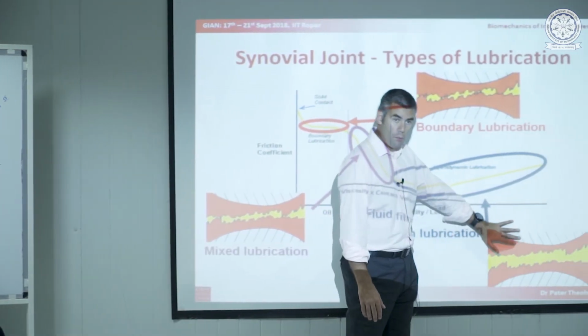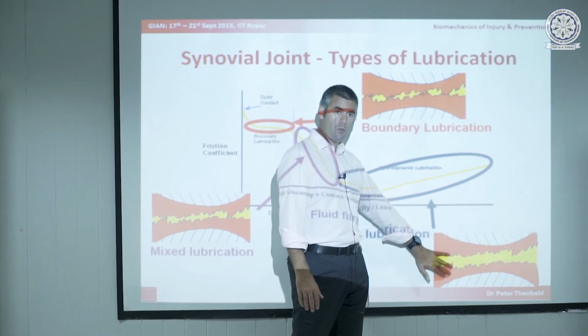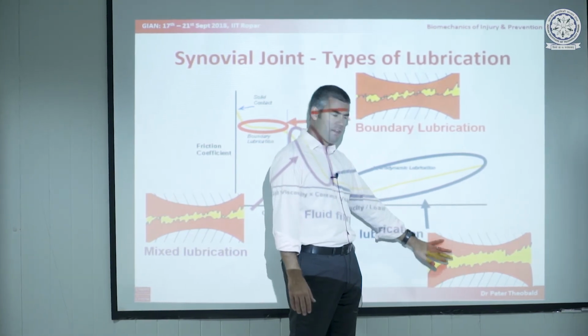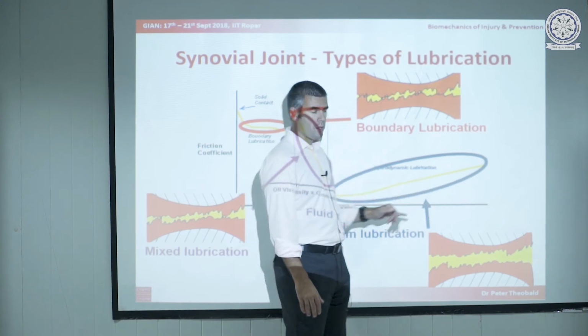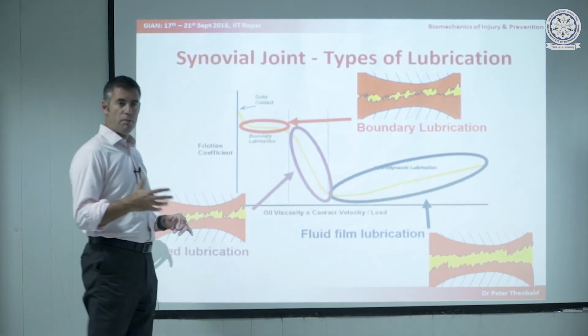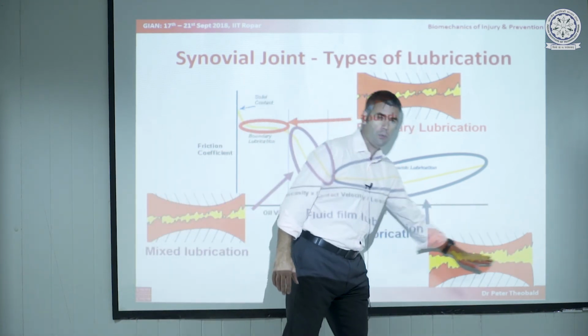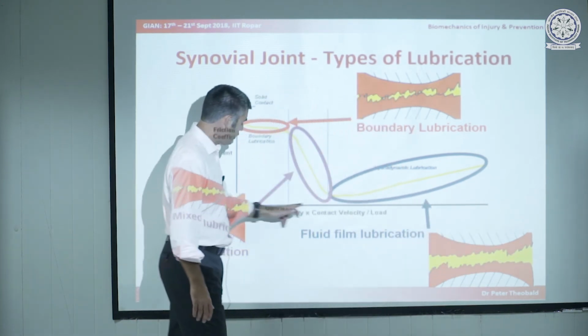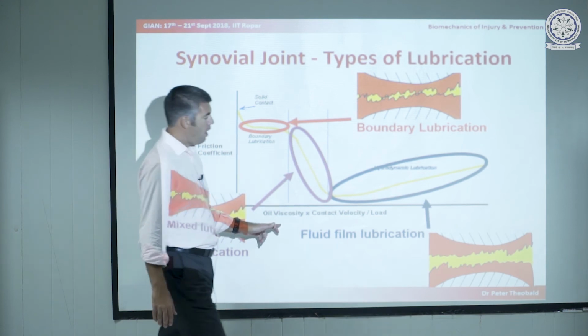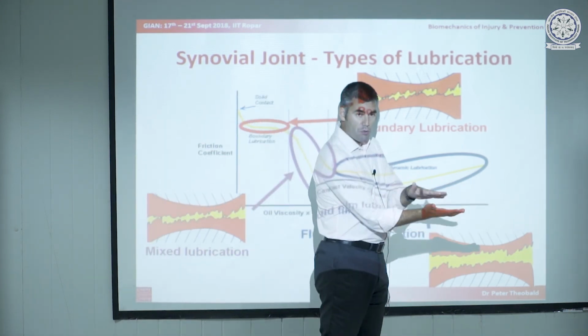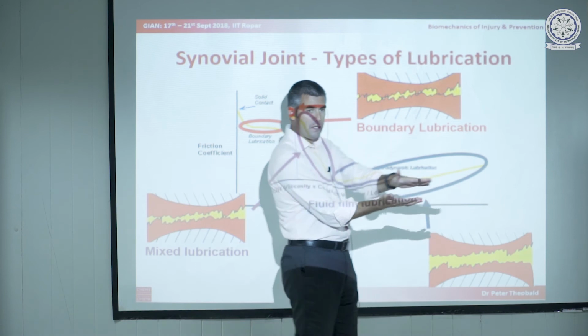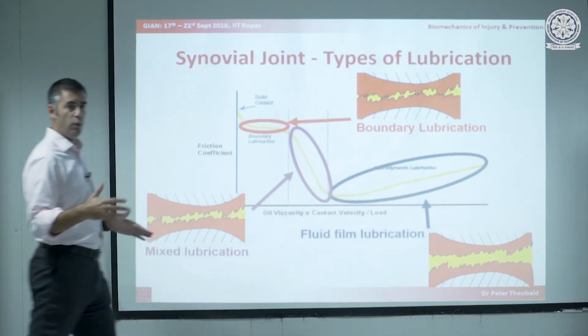That's right. So here we've got no contact between the two surfaces at all. And your question is, if there's no contact, then how can you have any friction at all? You still have some inherent resistance from the material itself. And so if you've got a very sticky fluid between the two, because it must be sticky because you've increased the viscosity, then you're going to get some inherent resistance as you try and slide one past the other because of the stickiness of the fluid.